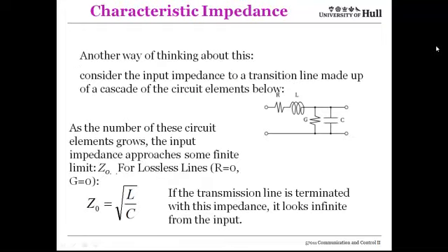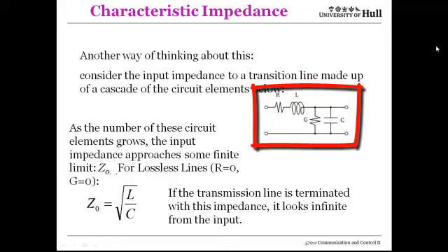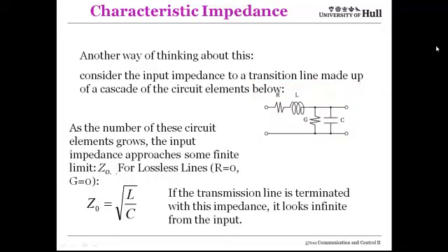If you think about this lumped circuit model for a transmission line that we saw earlier, this is the model where a short bit of transmission line is represented by lumped components of the resistance, inductance, capacitance and conductance per unit length, as in this diagram here. The resistance in the line will cause ohmic heating, and that will lead to losses. The voltage and the current will reduce as a wave propagates along a line where the resistance is non-zero. Similarly, if this conductance path between the forward and backward conduction routes is non-zero, then some of the signal will leak through this conductance before it gets to the end of the transmission line. So once again, the voltage and the current will decrease as it propagates.